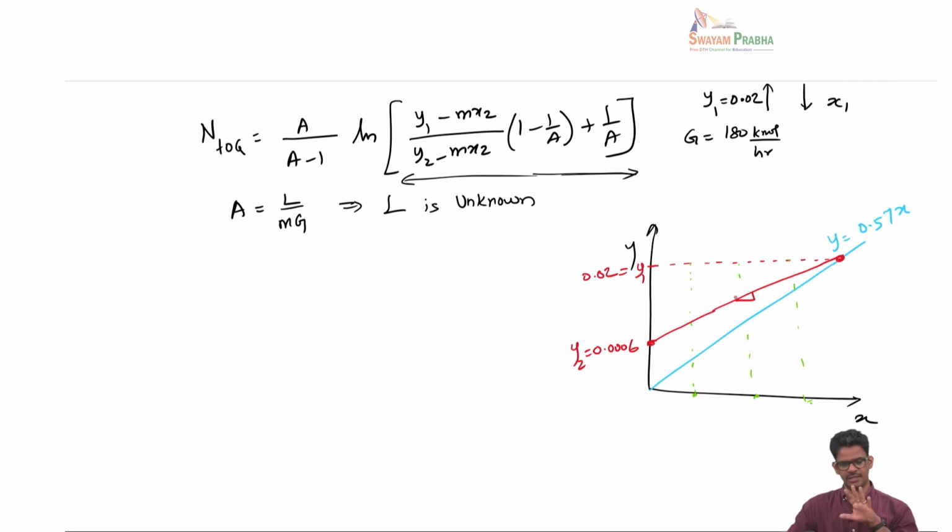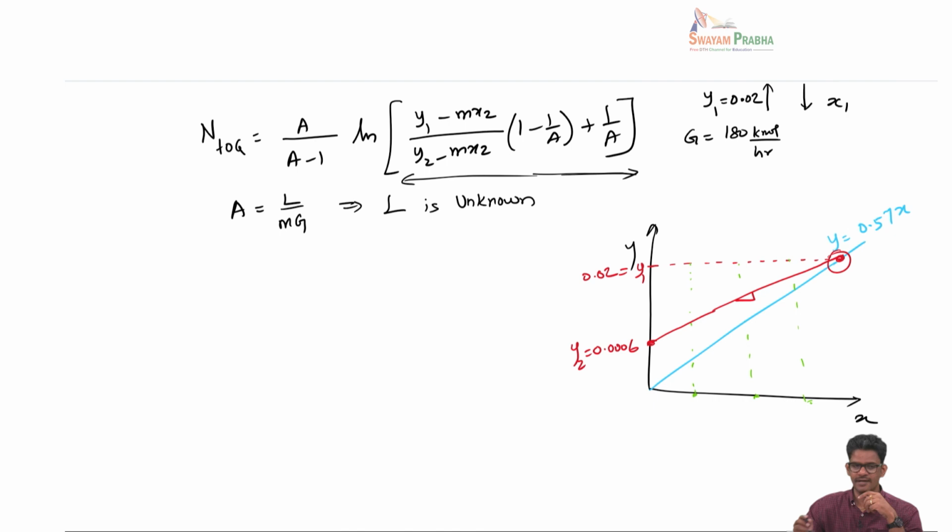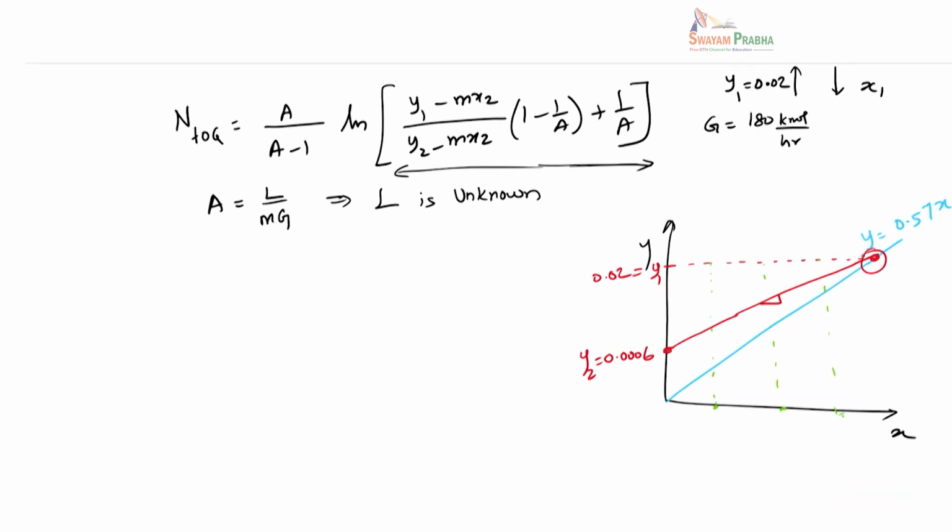Now you can do this, but be a little bit careful about this. Let's say you find this LS minimum and then you go to calculate A, I call it A minimum. And then if you go to this logarithmic term, you will see this term will blow up, because when you go close to this point, the average driving force vanishes.